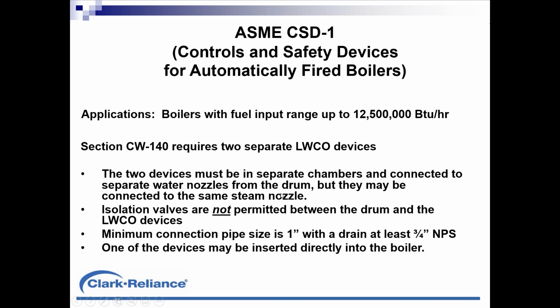It was mentioned earlier that I'm a member of CSD1. ASME CSD1 is a publication for controls and safety devices for automatically fired boilers. These rules apply to boilers that have a fuel input range up to 12,500,000 BTU per hour. The subsection of CSD1 that covers low water cutouts on steam boilers is CW140.